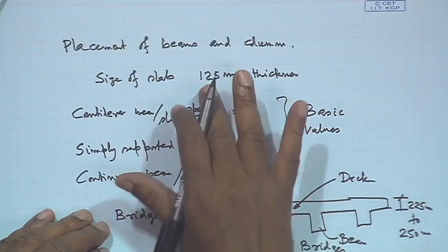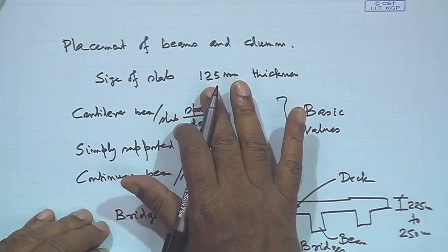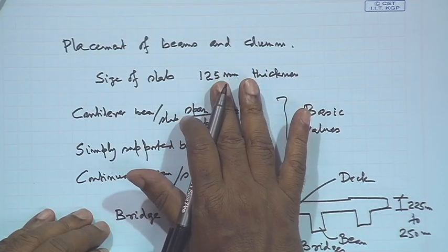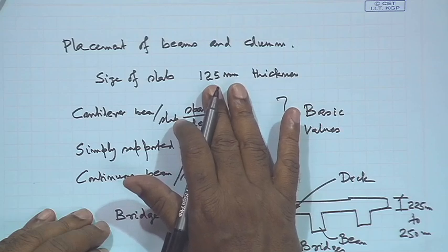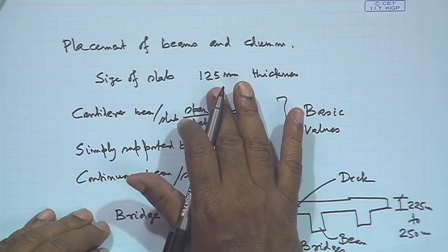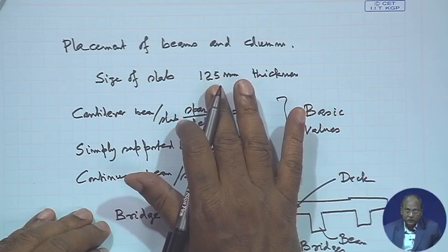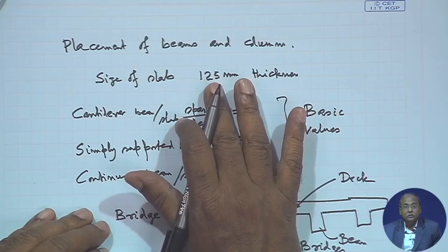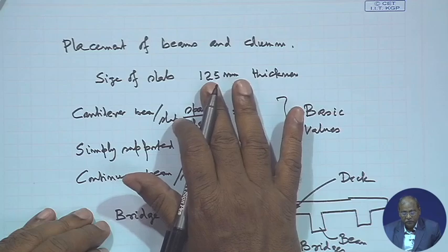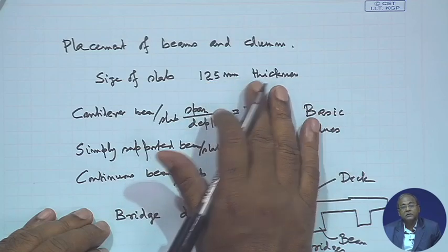Now, the question is about 125 mm: whenever we say we shall not give more than that, how shall we restrict it? It is dependent on the span. So, if we are increasing the span, we shall stop where the span gives you a larger slab depth.